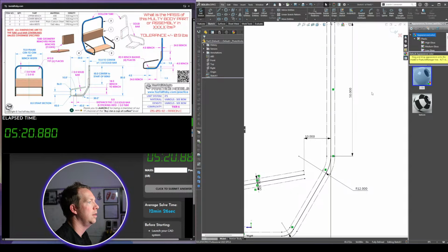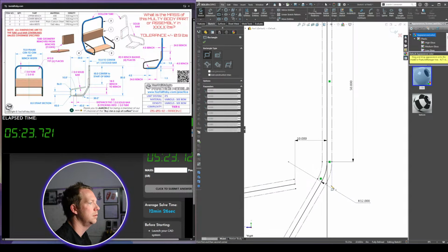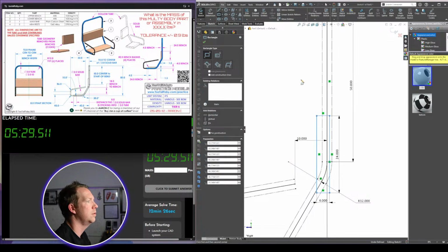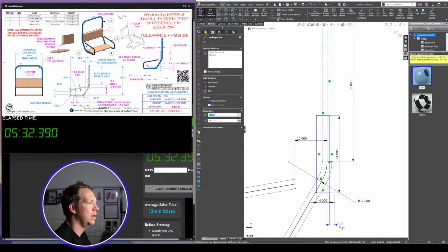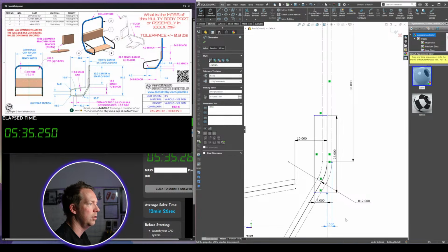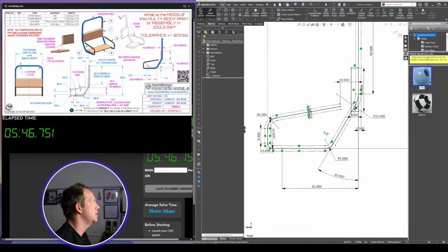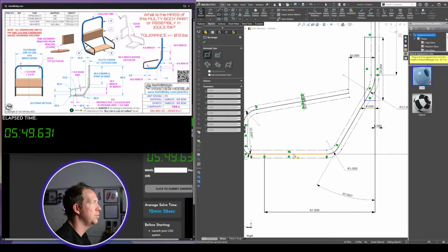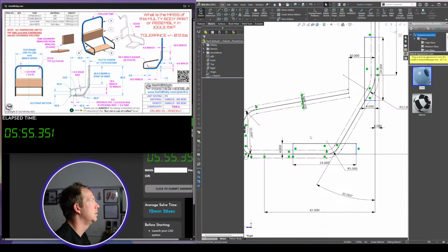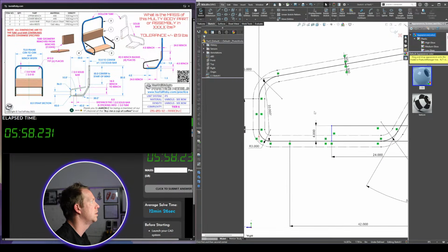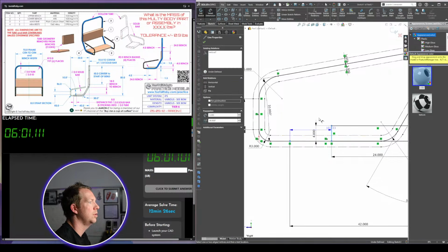Now with our tube outline, we can do our bench seat, which is like this. The bench seat is 24 by 4. It is offset 1.5 from the back. Got to make sure I'm not going too far over the edge. 1.5 from the back means it's on the center line, which would have made things a lot easier if I'd just done that to start. So the other one we can just put on that center line, and the dimension of that is 4 by 24. So that bench is 4 millimeters from that point of the tube.